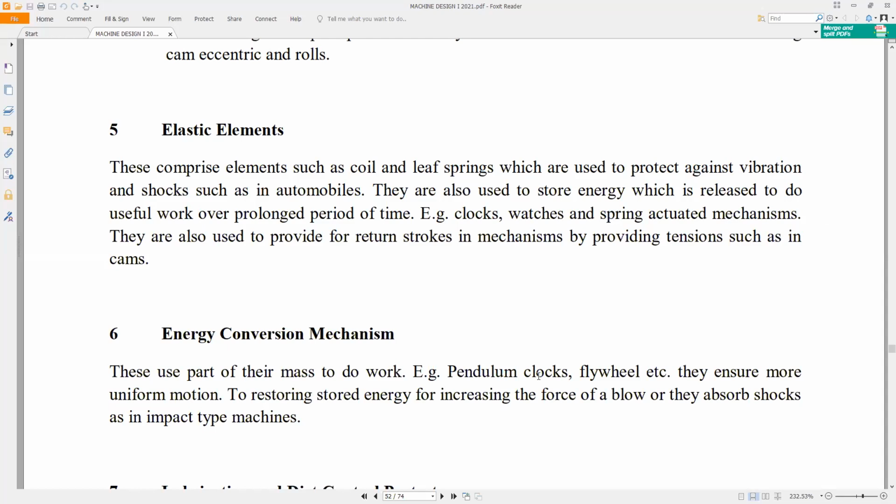at a point there is firing, there is power, it is producing power. And at a point it's the exhaust stroke. The exhaust valve has to open for the exhaust gases to go out. At that point, no power is being produced. So if you take the four-stroke engine, for instance, we only have one power stroke out of four strokes.